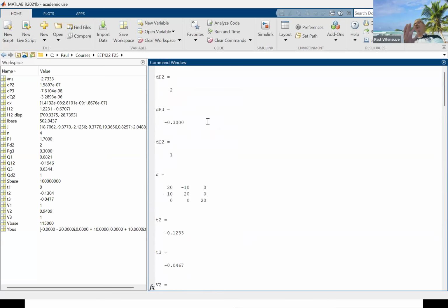So it starts off here, way off, right? With my DPs and my DQs all off. Here's my Jacobian. And the nice thing about the Jacobian is, if you have 1 at an angle of 0 for all your voltages, your initial guesses, your Jacobian is basically just your Y bus, right? These elements here are Y bus. You have zeros here and here, because remember, we're not sensitive to real power changes because of the voltage magnitude.